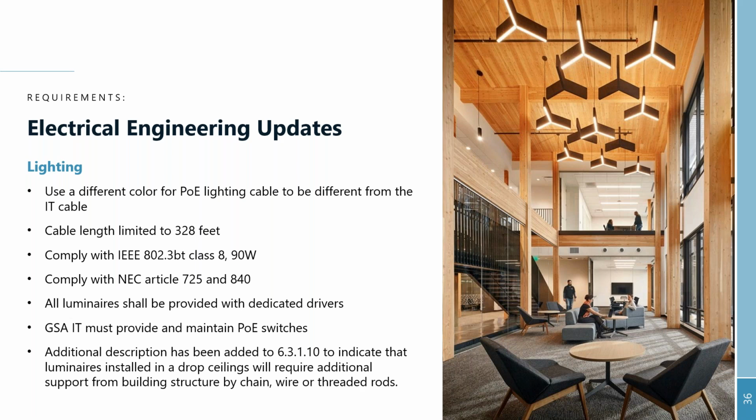Although it is not included in 2024 P100, there is a new player on the market called XPoE, and for that player you don't have to have dedicated drivers for each light, because the driver itself is located in a central location inside the LAN rooms, in the racks. So that makes the PoE system, or the XPoE system, much more flexible and easier to install and maintain.